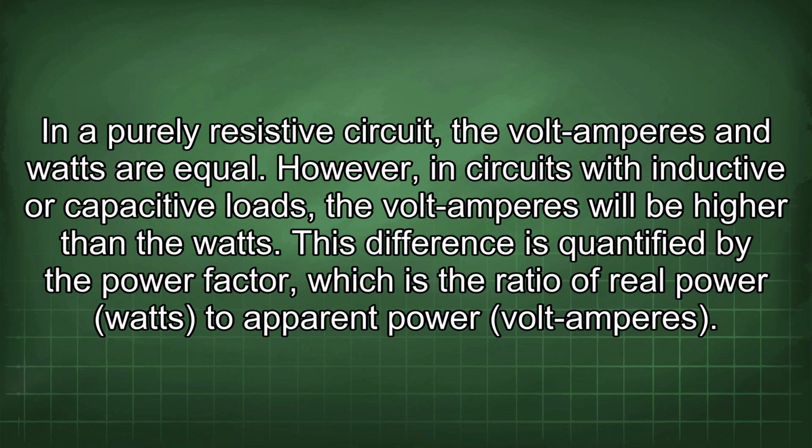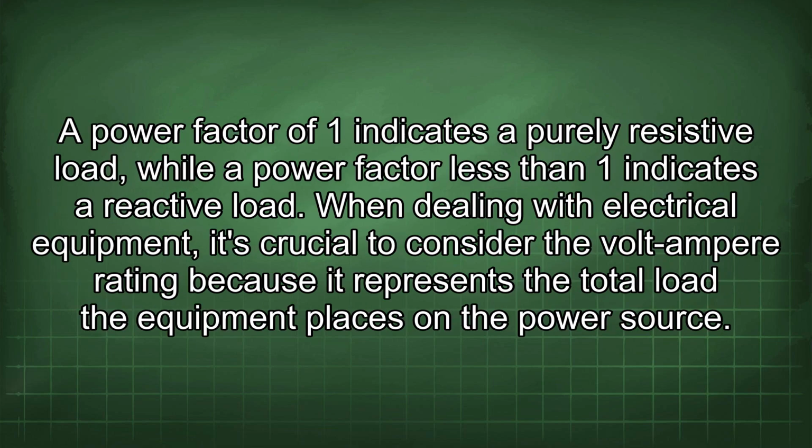In a purely resistive circuit, the volt-amperes and watts are equal. However, in circuits with inductive or capacitive loads, the volt-amperes will be higher than the watts. This difference is quantified by the power factor, which is the ratio of real power watts to apparent power volt-amperes. A power factor of 1 indicates a purely resistive load, while a power factor less than 1 indicates a reactive load.